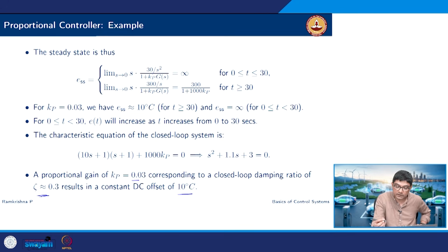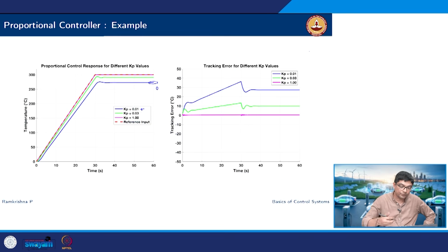So, now what does the first statement mean? The first statement means that if I'm just having a reference as a ramp, at steady state the proportional control will only fall away, and you can see in these pictures also that the distance between the green and the blue curves is kind of increasing. So, as time progresses, the distance will just diverge and the steady state error will be infinity. However, at this point my reference changes, and that makes things a little easier for me. It will actually be a step reference from then on.